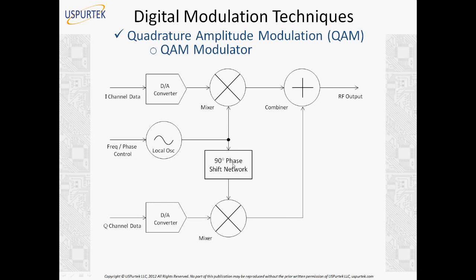So the first one is only data. This is not yet an analog signal, and it is not yet shifted. You have to actually shift the signal by having a 90 degree phase shift network. So we are not doing it again. Previously, we are only separating the two streams: which data will go into the I signal and which data will go into the Q signal. It is not the actual signal which is phase shifted. Phase shift happens here when the local oscillator frequency is phase shifted by 90 degrees. That is how we get the cosine signal.